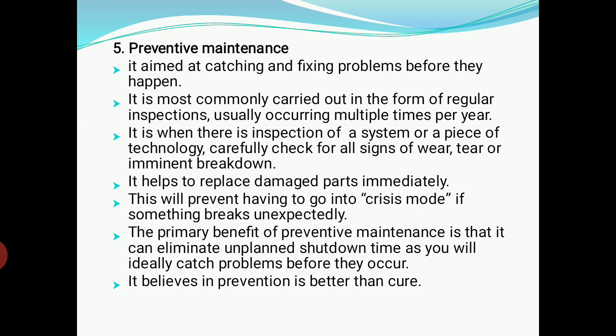Next, the last one is preventive maintenance. The name itself tells you that prevention is better than cure. That means before anything occurs, we are taking care of it. We are trying to see that we are keeping every facility and every kind of machine in a better condition, so that no major breakdowns are there, no major shutdown is required. So this type of preventive maintenance is also taken up many a times by the manufacturer.